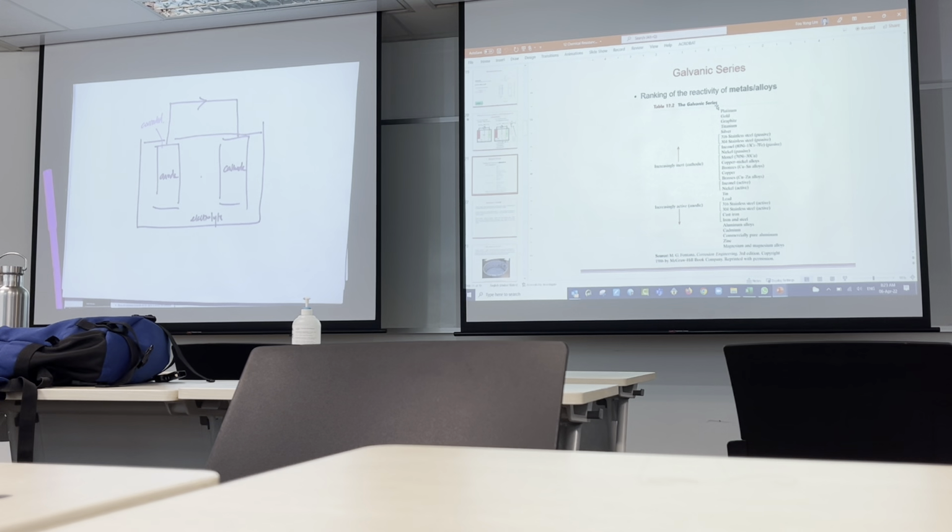So in the galvanic series, we start to put in more real engineering material. So instead of iron, we put steel. We can put cast iron. So those are things that we use. And the reason why I told you we use alloy is a very simple idea: mechanically stronger. Because nobody will want to use iron by itself. People will use steel. Nickel or whatever, Monel, these are basically your super alloys. These are the whole reason why we use them.